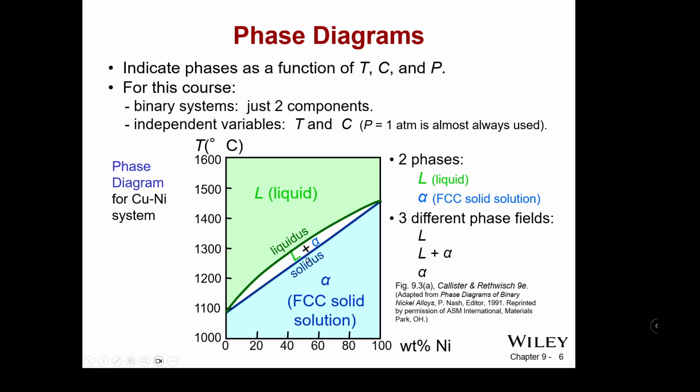So even though it starts to melt at 1250, we have to reach a full 1300 at that ratio. Same thing over here, about 70%. We hit that just a little over 1300, probably 1320 degrees. And then as we continue heating, we have a mixture of liquid and solid. And then about here, somewhere around 1380 or so, we reach the liquid envelope.